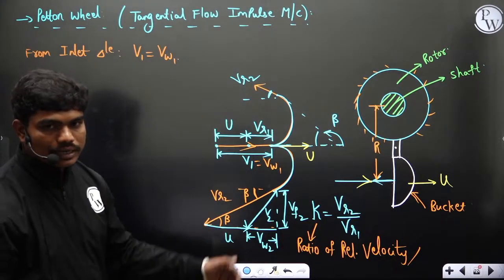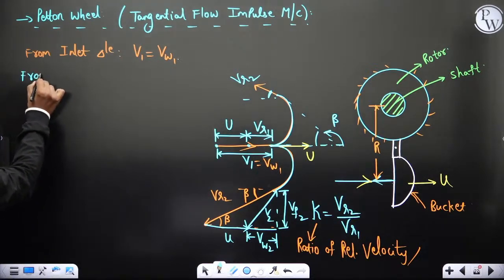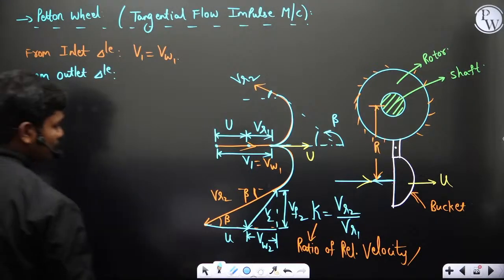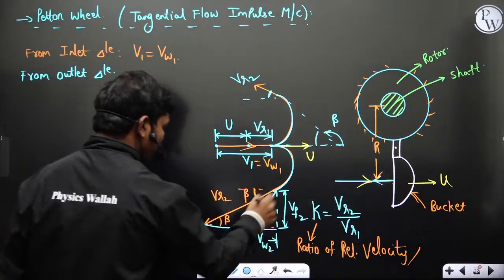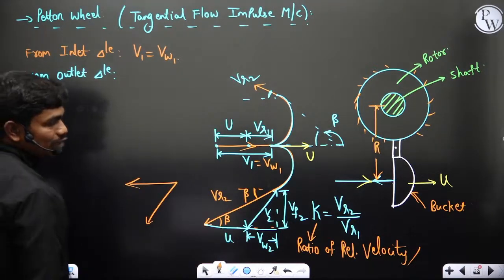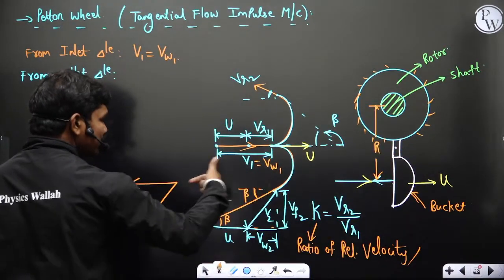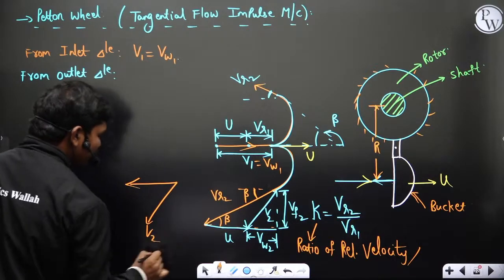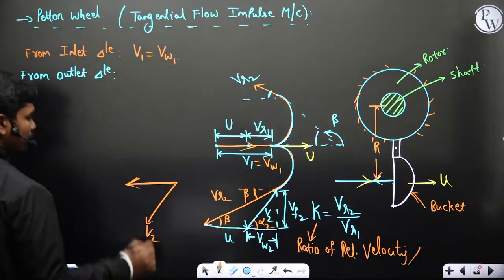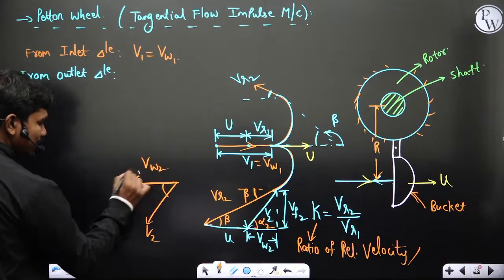Now let us see, since you should know what is the power which should be transferred to this Pelton wheel actually. So from the outlet angle, clearly one thing is very sure. If you resolve a velocity which is in this direction, the x component, the tangential component, will be in the negative direction, yes or no? Because completely the blade is moving in this direction, but this outlet velocity is in the reverse direction because v2 is in this way. So clearly, if you call this angle alpha 2, then this x component of velocity, the tangential component vw2, will have a sense in the negative direction.